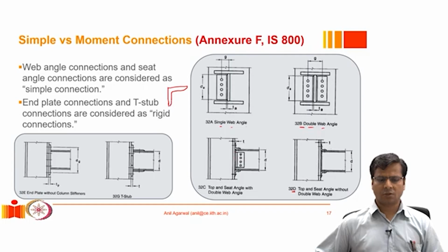This is the angle geometry, and the beam's bottom flange is sitting somewhere here like this, right? Because of that, this portion of the angle has to resist this load, and that will produce a very large bending moment demand or a shear force demand at this cross section of the angle that I have just drawn, right? So in order for it to resist that load better, sometimes we may put a stiffener here. That stiffener will basically strengthen the angle.